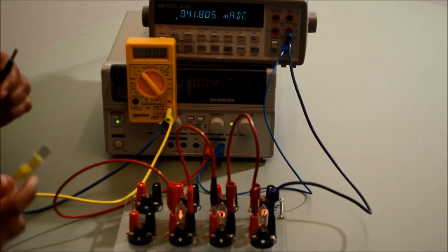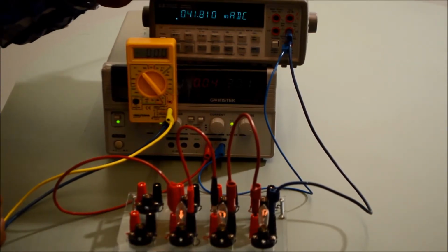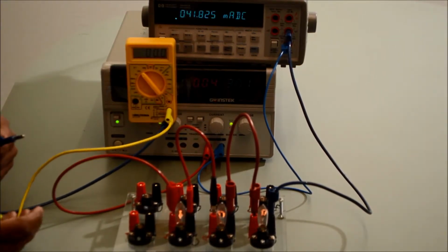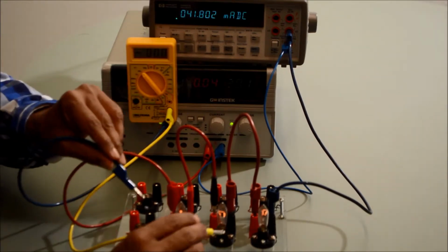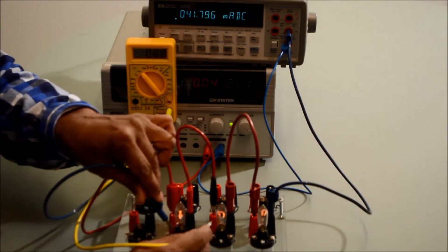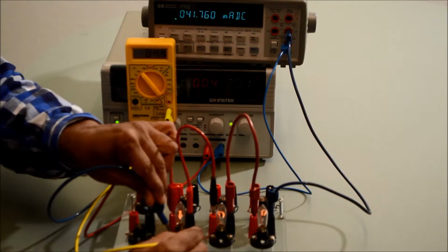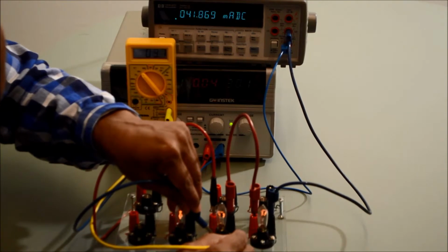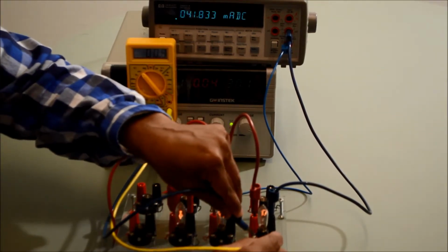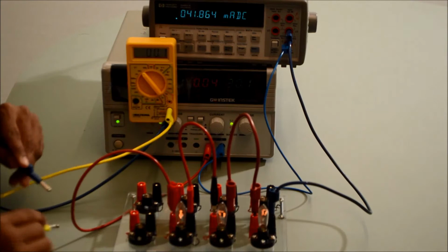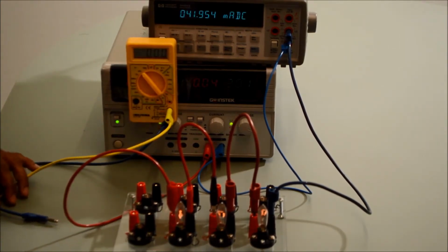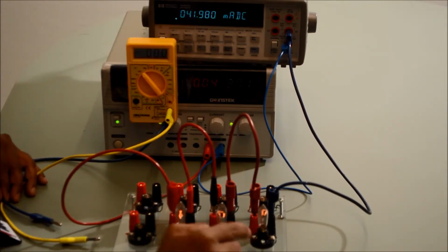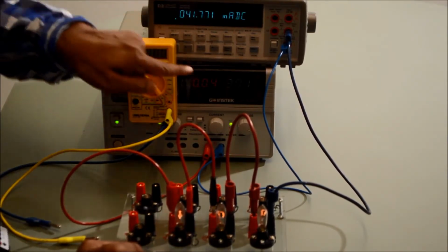And at last we want to see how this voltage, 30 volt, has been distributed over the lamps. We have 3 lamps connected. Now if I measure the voltage over the lamps, here I have about 10 volt, 10.2, here 9.7, and here 10. So we see that we get about 10, 10, 10. So in total we have 30 volt.